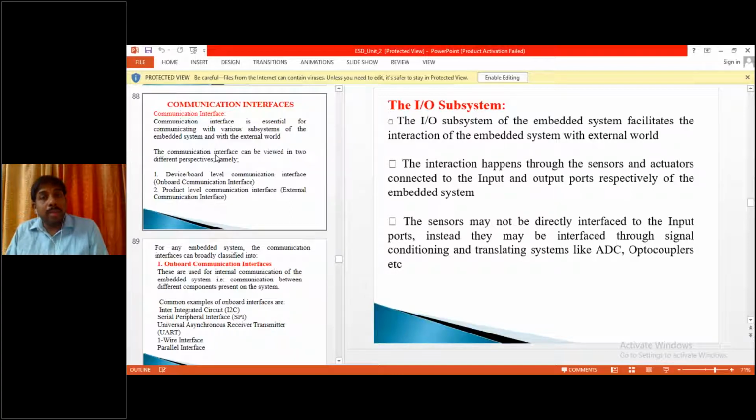And in order to achieve that temperature, it will take the difference between the temperature of the room and the temperature set by the user, and this data is sent as a control signal to your actuator. The actuator will run the output motors, due to which air flows into the room, and like that cooling occurs. Once the room attains the exact temperature, the motors automatically get switched off, because the control signal is stopped from the processor.